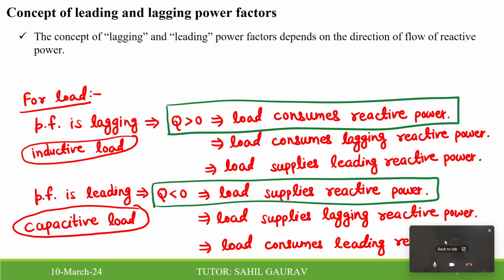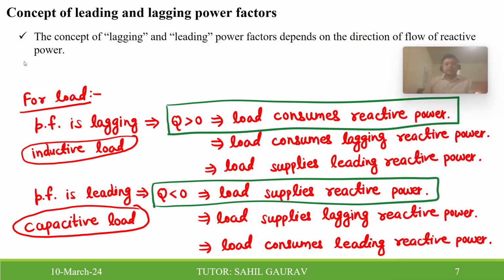Now these are very important: the concept of leading and lagging power factors. The concept of lagging or leading power factor depends on the direction of flow of reactive power. And for a load, if the power factor is lagging, that denotes that it is inductive in nature.